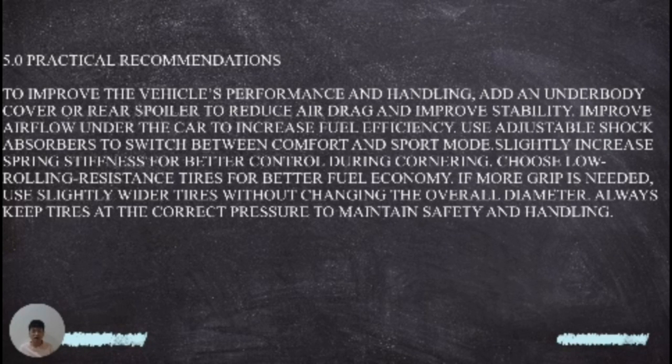Choose lower rolling resistance tires for better fuel economy. If more grip is needed, use slightly wider tires without changing the overall diameter. And lastly, always maintain the correct tire pressure to ensure safety and handling.